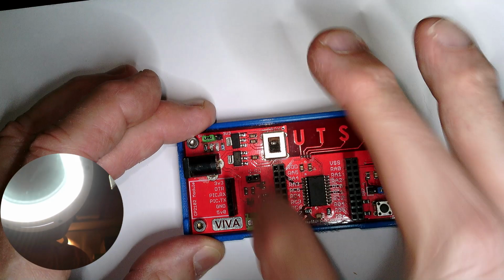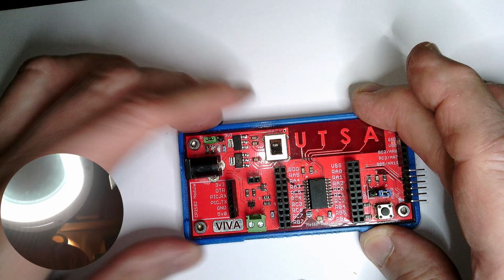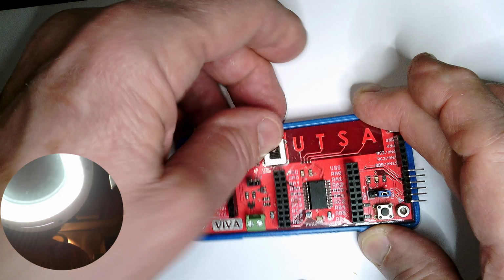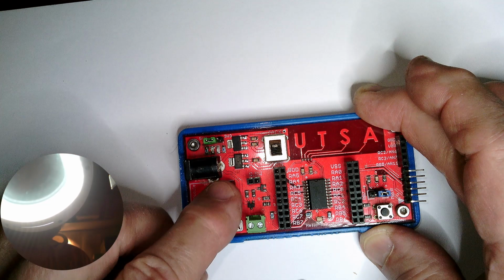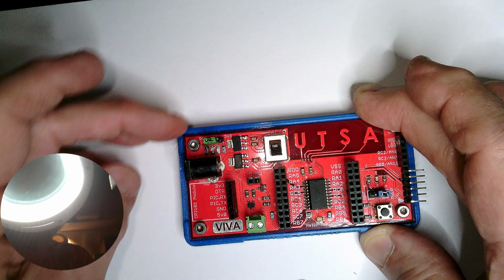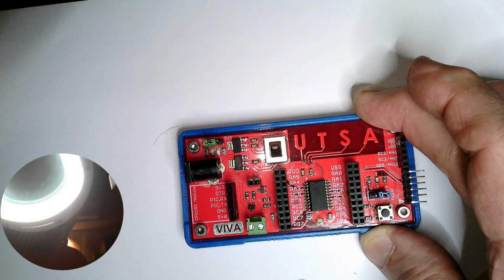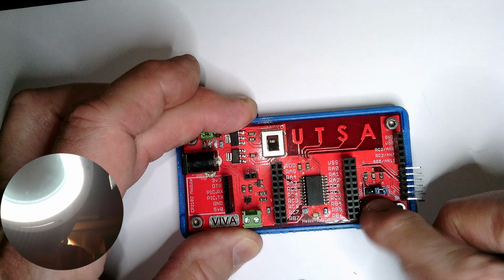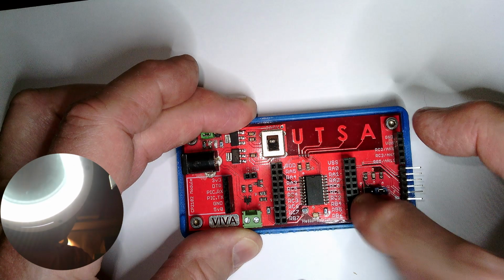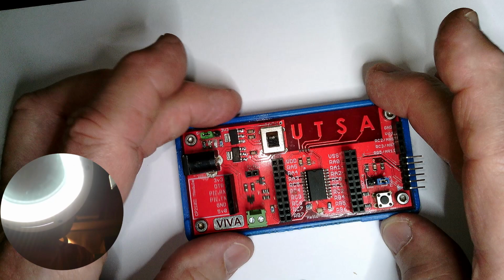And we have a 2 transistor switch here and some voltage regulators here, power input here, and a switch that switches between the battery or the CP2102 header, and we can jumper here from 5 volts to 3.3 volts. And we can jumper here. We have a push button. It can be a master clear, or it can be jumpered over here to be an RB7 input.